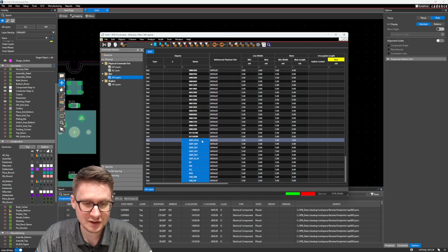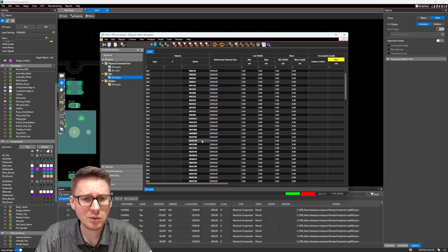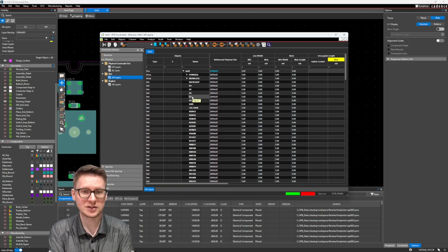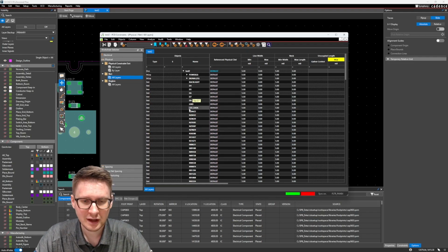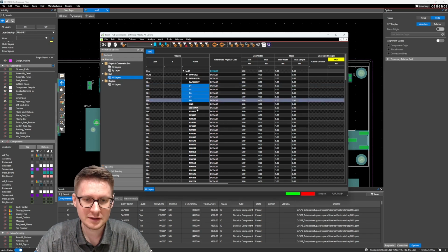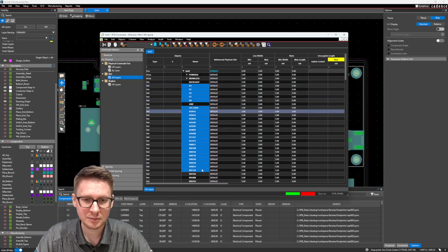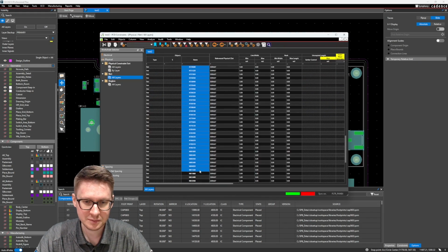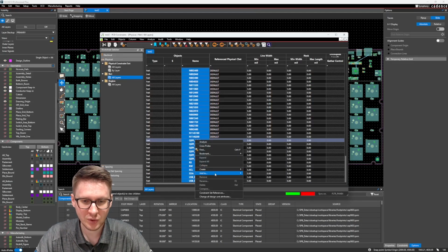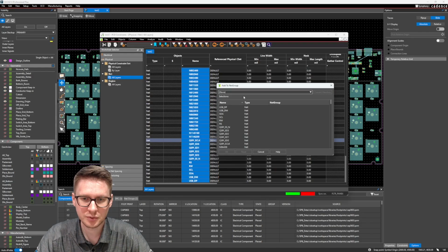Let's just go ahead and select these. And I would treat these as regular digital signals as well. We have the data lines for our LCD, an enable line, LED data. These would all qualify as, again, signal nets. So let's go to the bottom here, right click, and we want to, in this case, add to net group, choose the signal net group and click OK.